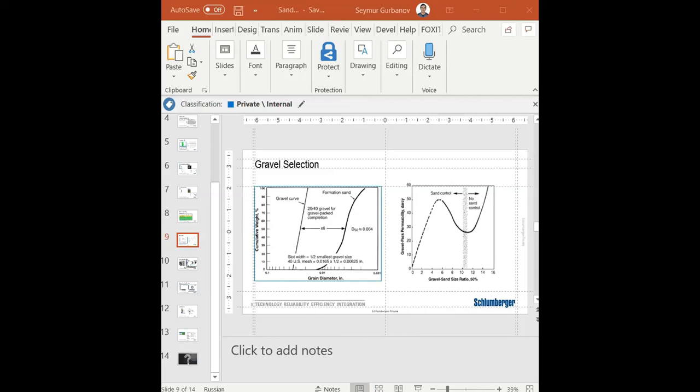But if you're talking about a method to see it in bottom hole conditions, there are two ways. There is the wireline tool, which does the same. It measures the noise created by sand which hits the metal. You run the special tool across your intervals, and in the zone where you have sand, the sand hits that tool, and the tool registers exactly from which interval the sand is produced.